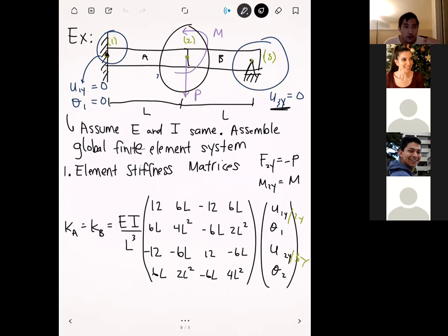So that means both its displacement and its rotation are being constrained. In fact, they're being set to 0, right? And so because of that, there's going to be a force that the support applies onto the beam, basically in order to keep it in static equilibrium. And so whenever you have a support that constrains some kind of movement, there should be a reaction force there that prevents that specific movement. Okay, thank you. Mm-hmm.